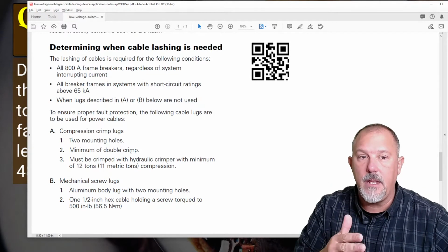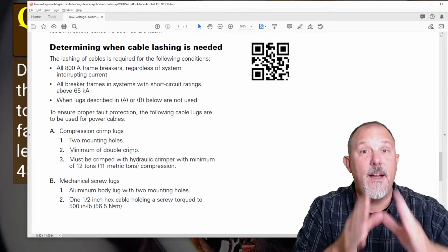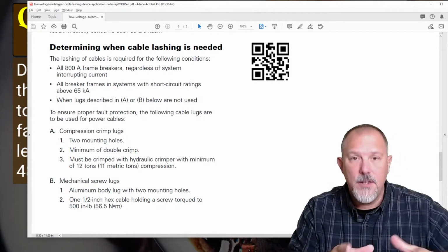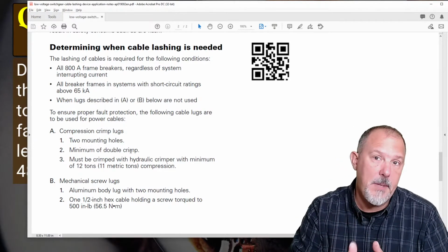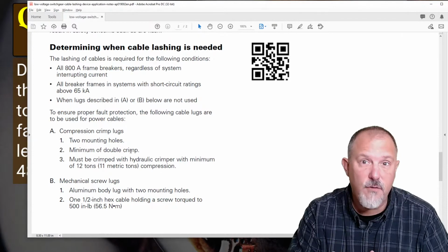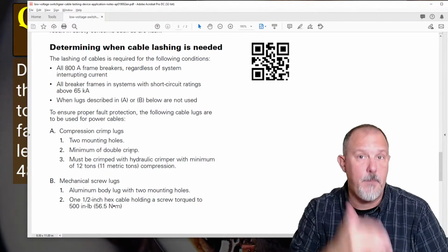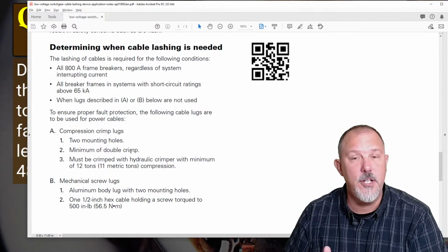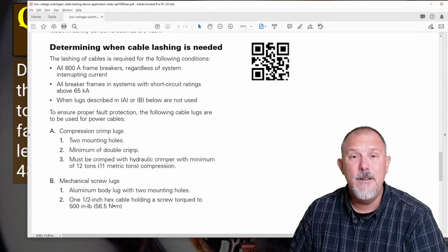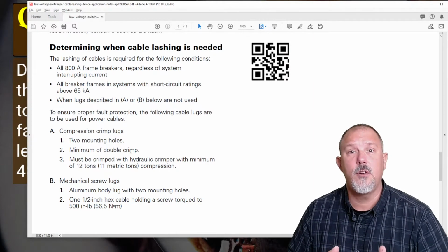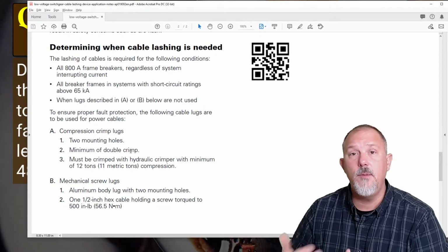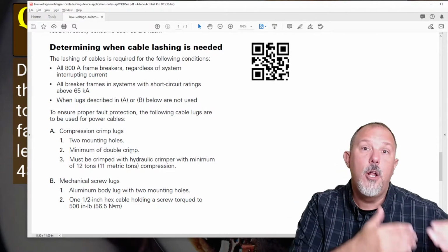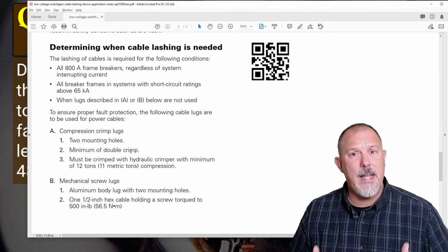You have to understand, when you're adding those intentional delays, when those fault currents are very high, and you have those high peak currents, and you're going to let those things flow because you're not reducing the peak, you're not in the current limiting region of an overcurrent protective device, magnetic forces can do a lot of damage in equipment. Which tells us when we have these high fault currents downstream, we may want to look at our system, look at the equipment before we start re-energizing.